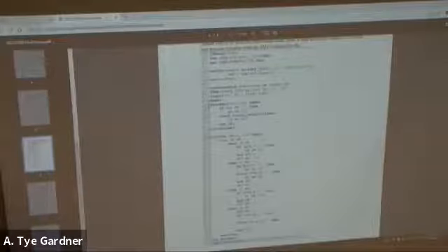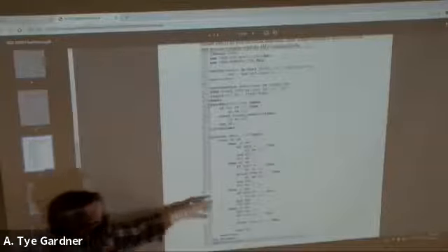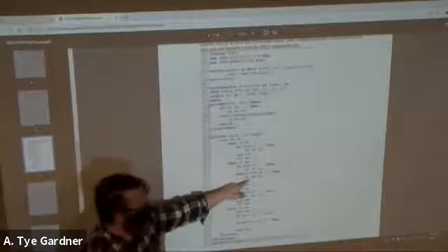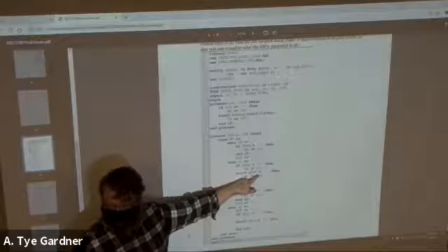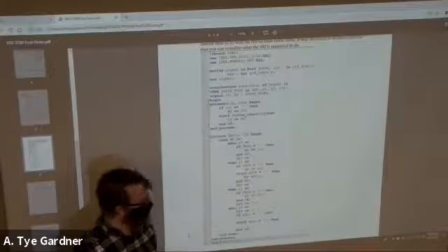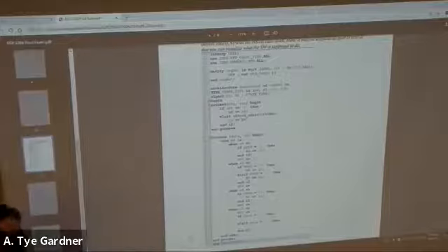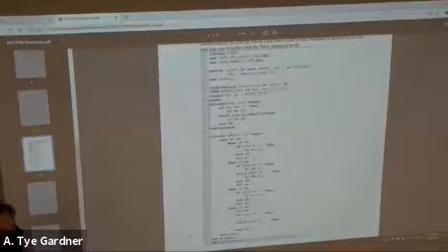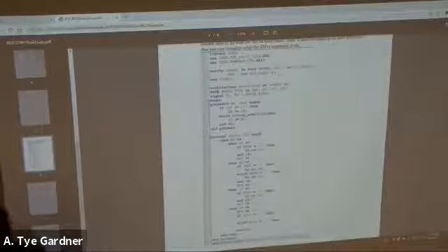Yes, state 1 doesn't do what it's supposed to do. Right. So state 1, which is B, is if I get a 1, I stay in B. But in the code, state 1, if I get a 1, I go back to state 0. This is functionally wrong. Wait, wouldn't it just be an else statement, not else if? Else or else if. Okay, they both work.